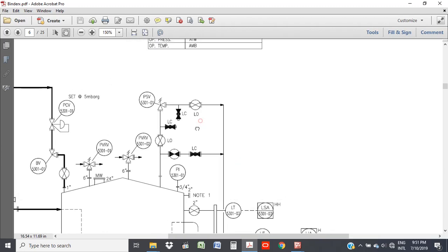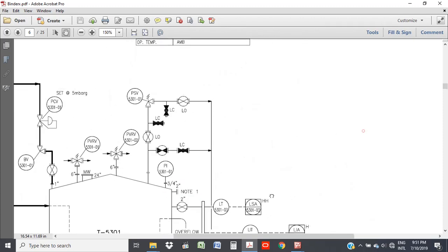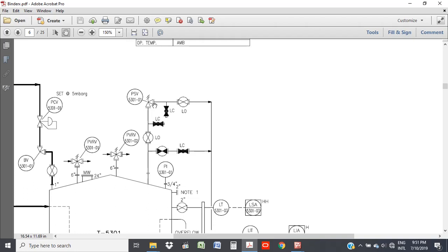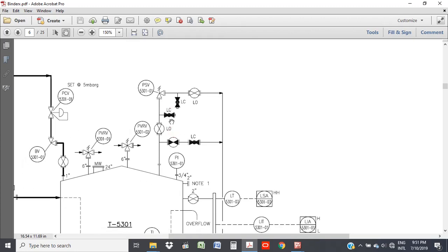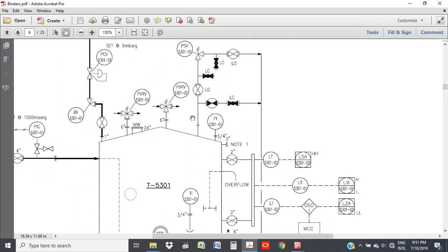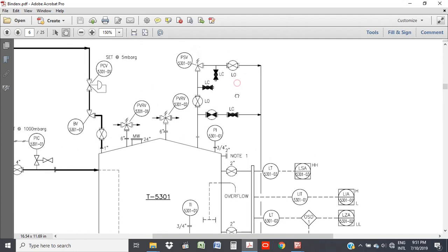Sometimes they're in that position for years. What you want in such a situation is that those valves don't get opened or closed by people just going there and making an error, because you have so many valves around, and if the P&IDs are not read well, and the labeling on the tags on the valves is not read well, you might actually have them mistakenly opened or closed. So that's talking about opening or closing valves.